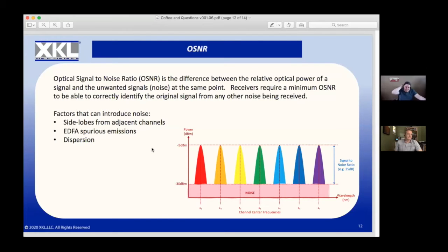Now, forward error correction, I just noticed that one. Is forward error correction applied to layer 1 fiber optic transmission? Yes, it is for some technologies. Now, I mentioned before about it getting faster and faster with the 100 gigabits, 200, 400. Now you hear about vendors out there with 800 gigabit optical circuits. They're using coherent modulation technologies. And typically, yes, coherent services do use forward error correction.